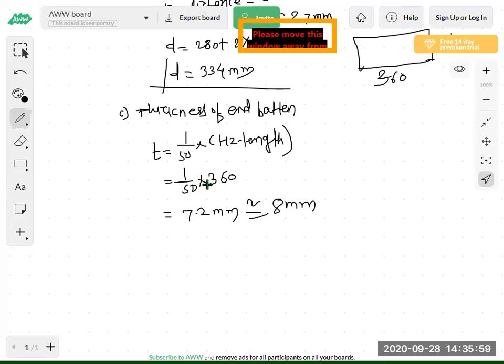Now here if we use 420, for example if we add BF/2 it becomes 420, and then only the thickness will increase. So the thickness depends upon the length. And here, again, length of batten that we have already calculated, that is L is equal to S plus G, we have taken, so that is 360 mm already taken.